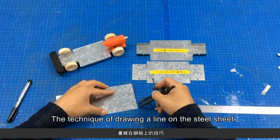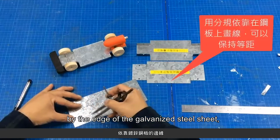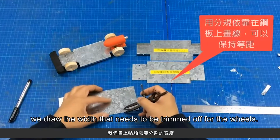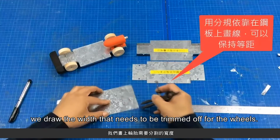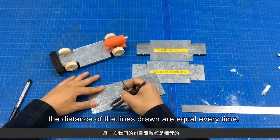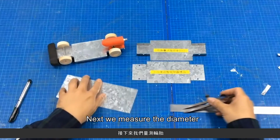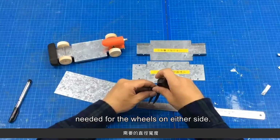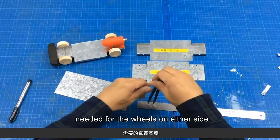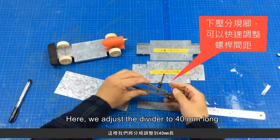The technique of drawing a line on the steel sheet: we can use the divider guided by the edge of the galvanized steel sheet. We draw the width that needs to be trimmed off for the wheels. The distance of the lines drawn is equal every time. Next, we measure the diameter needed for the wheels on either side. Here, we adjust the divider to 40 millimeters long.